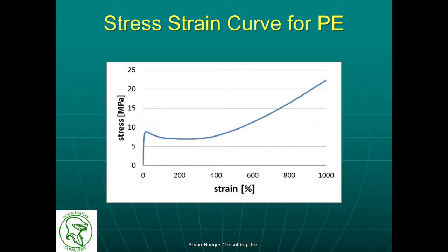In this example, the apparent stress at break is higher than the stress at yield. However, two features are of interest for our further discussions. One will be the natural draw ratio, and is the strain at which the load first increases following the region of fiber drawing. The second is termed the strain hardening modulus, and is the slope of the region with increasing load following the natural draw ratio. These are important concepts and will be referred to throughout the talk.